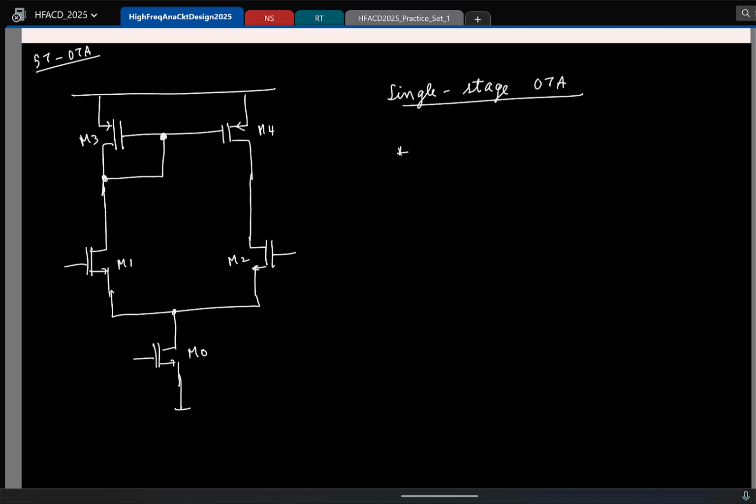So do you think this will be a good candidate if I have a resistive load? Assuming that you don't connect the resistor so that it disturbs the DC operating point. Let's say you put a large capacitor or connect the resistor's other end to a DC voltage source appropriately. But as we saw, even if you have an RL here, it affects the small signal gain. So it is not a great choice for resistive loads. Only if your resistance is really large compared to your existing output resistance, this works. Otherwise, it is not great.